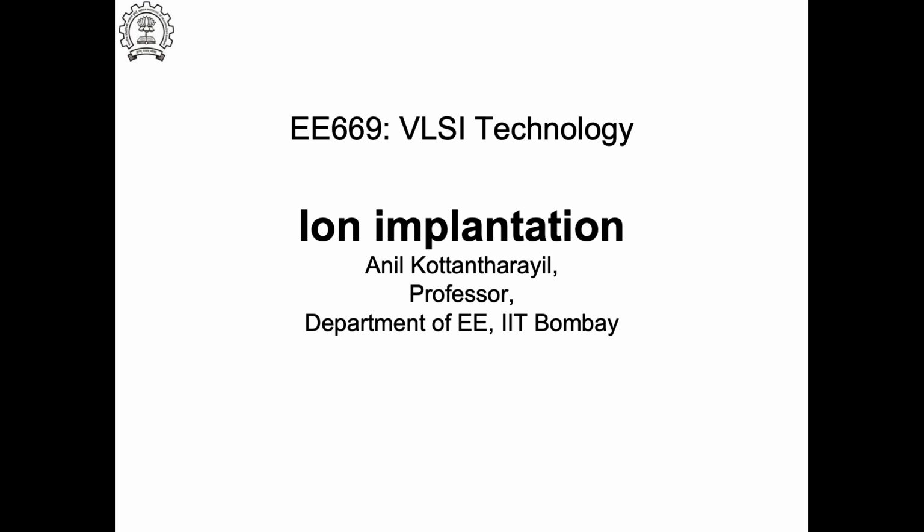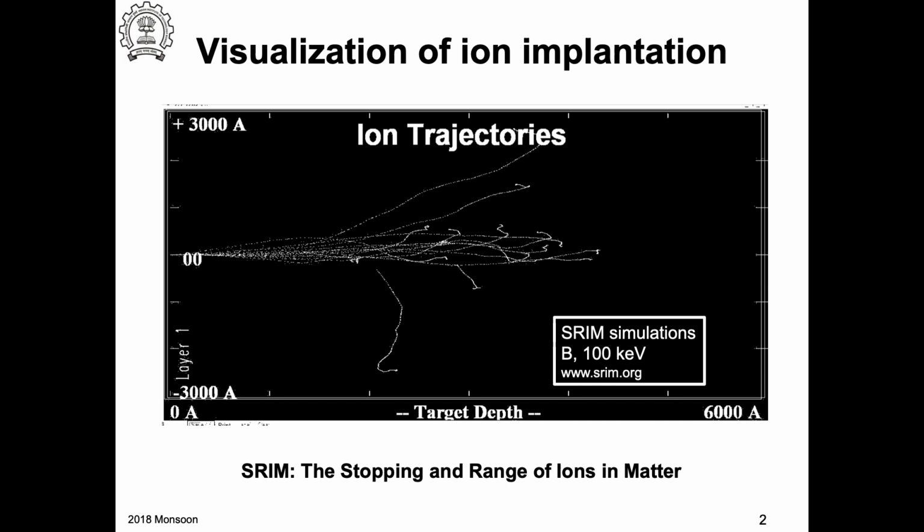So if I take this example, I want to implant this ion. What is uncertain about this process? You can think of a crystal and ions are implanted. Ions have high energy. What is probabilistic? Basically, the ions are going in and they see the atoms arranged inside this solid. Will they move in a straight line? No. They will interact with the particles inside the solid, and it can interact in different ways.